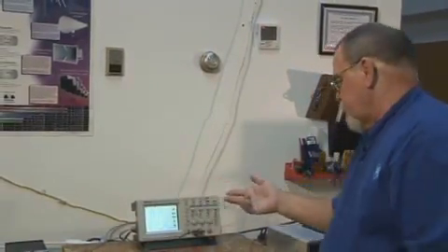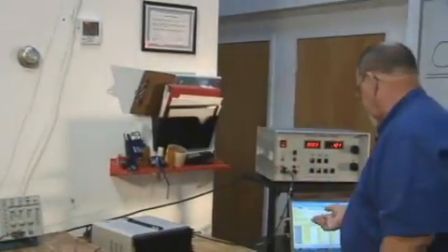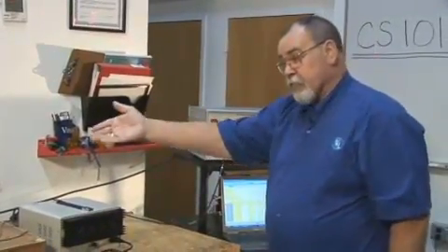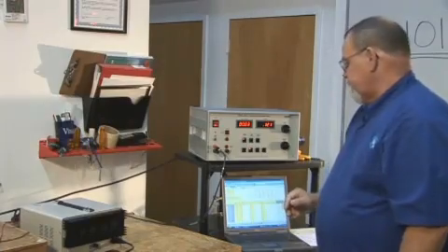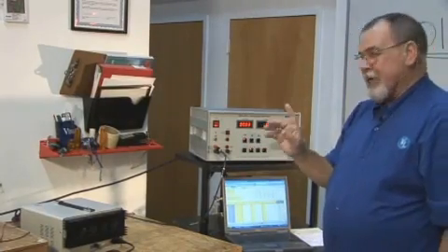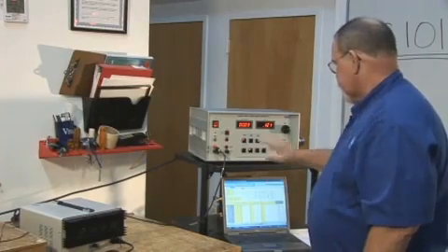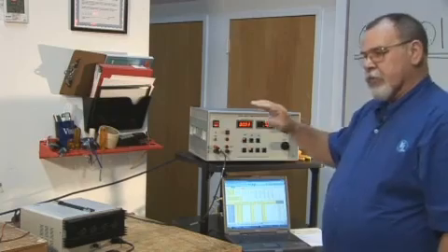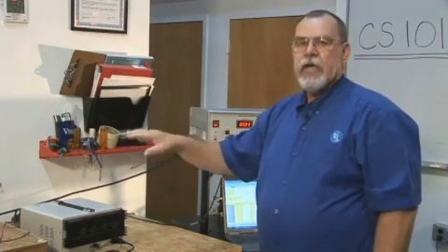When I go to the calculations, this is a curve 1 test limit. I've converted that into a volts peak to peak because I can't measure RMS, as we discussed. I need 17.8 volts peak to peak, but I don't exceed the pre-calibrated forward power, which was 13.9 volts out of my signal generator.